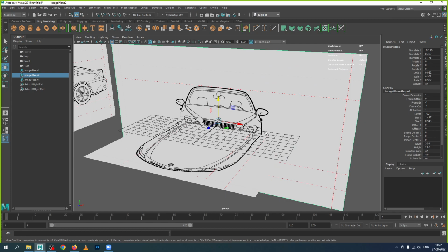Now the setting has to be done from the side view, front view and top view. These we have matched for what? Whether proportions are perfect or not for the reference image. But in that also we need to provide only one direction to move. That is up and down for adjusting the level. That's it. Don't disturb width, height, and don't scale this, don't rotate anything in that area. Only one way you have to move, either up or down, for balancing the level.